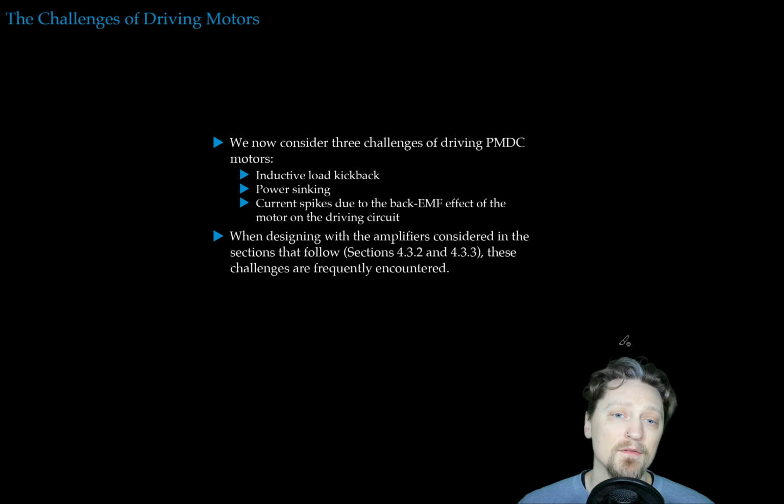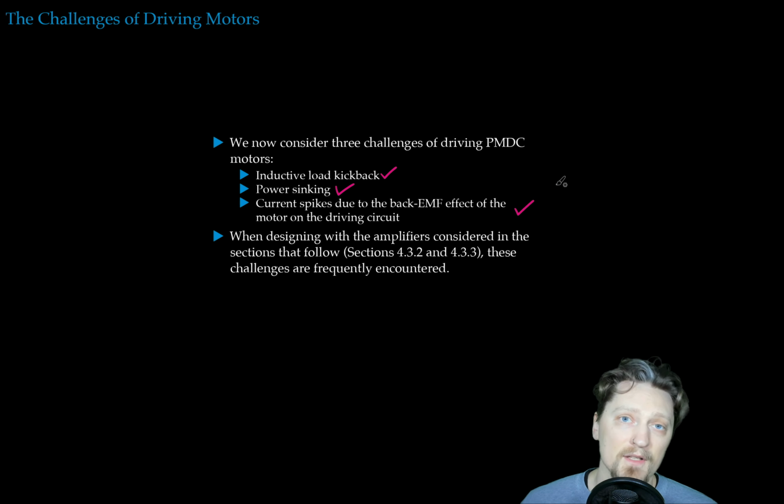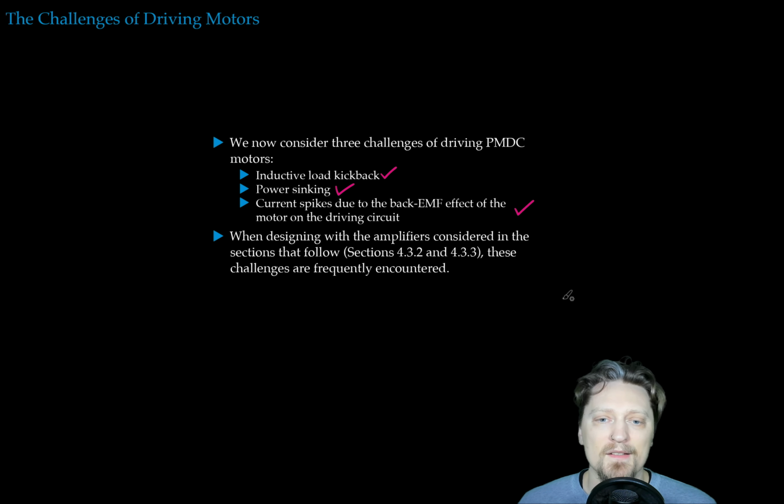Okay, the challenges of driving motors. We now consider 3 challenges of driving PMDC motors: inductive load kickback, power sinking, and current spikes or current transients due to the back EMF effect of the motor on the driving circuit. When designing with the amplifiers considered in the sections that follow, these challenges are frequently encountered, so we're going to take a look at them so that we understand them here.